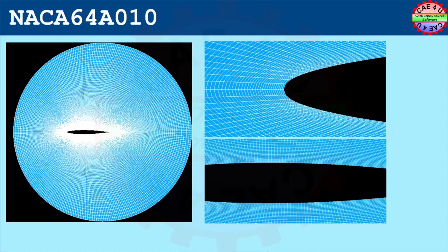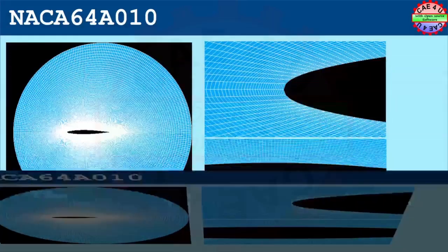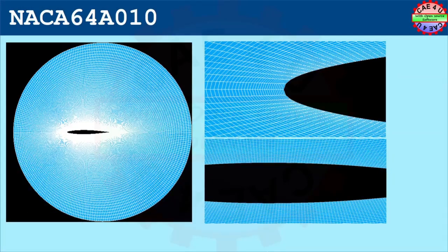We used the Salome platform for meshing. As usual, we also adopted a structured grid. The local refinements were indeed made, but not to the extent of respecting any targeted y plus value. Again, this is a scope for improvement, but for the current simulation, we will keep the simple grid that we have created.